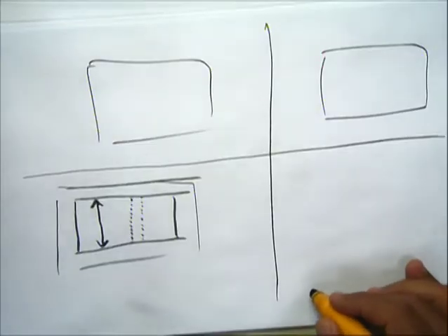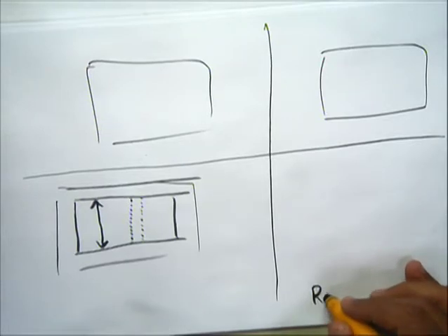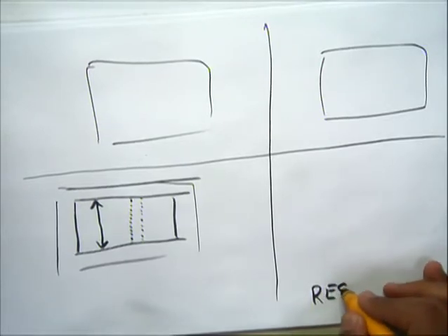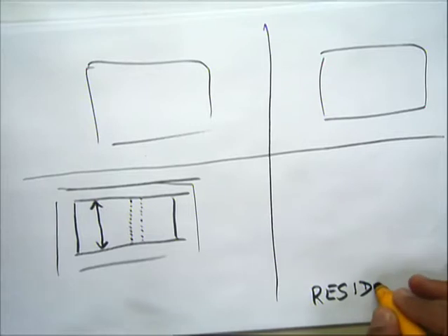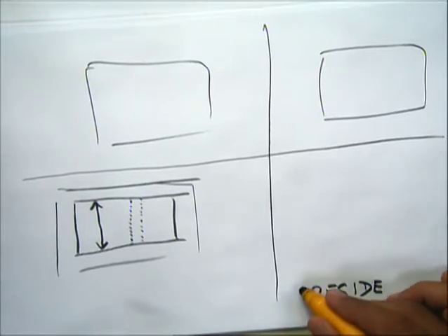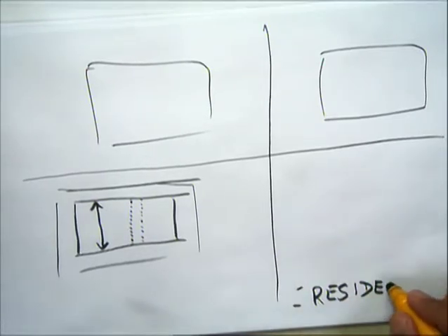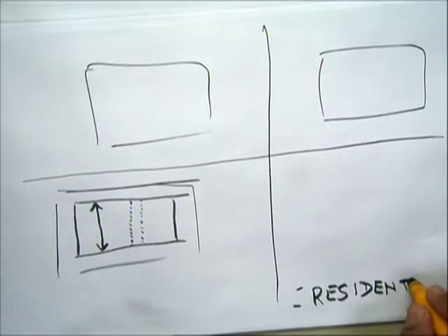So in any drawing sheet there will be three types of lettering. One is the title of the sheet, which will have the largest letter size. So we may put, this is a residential building, as the title of the sheet. The letter height will have the largest size.